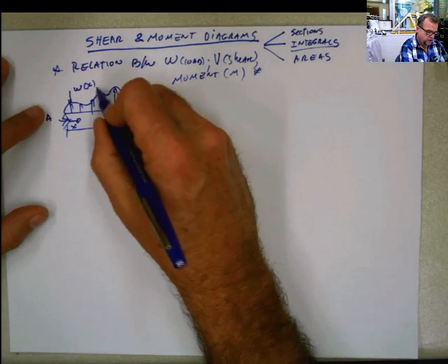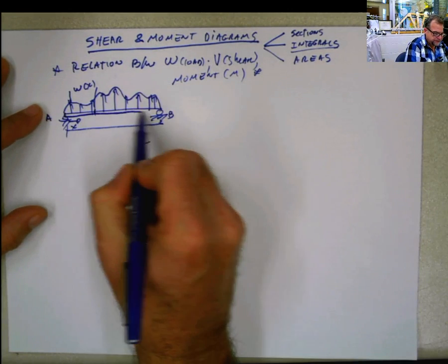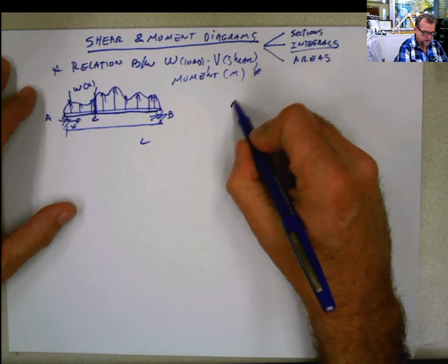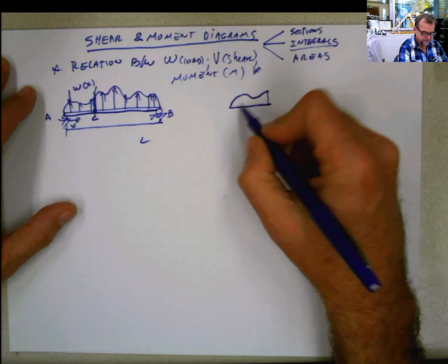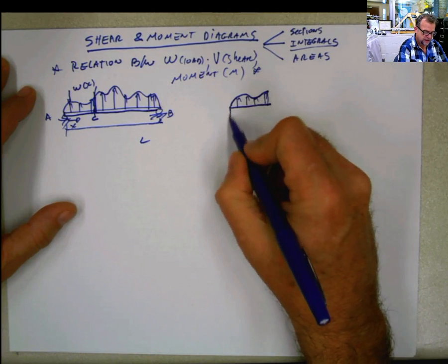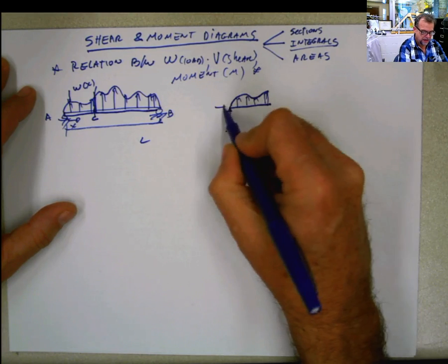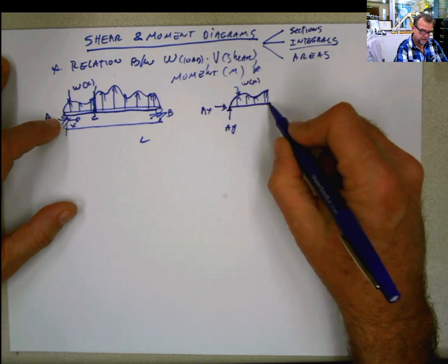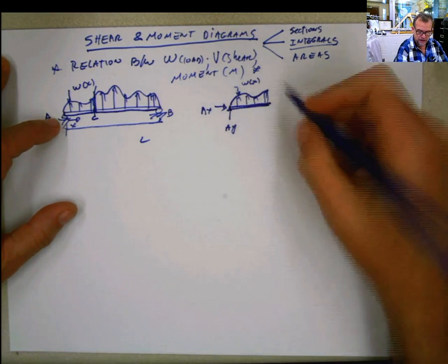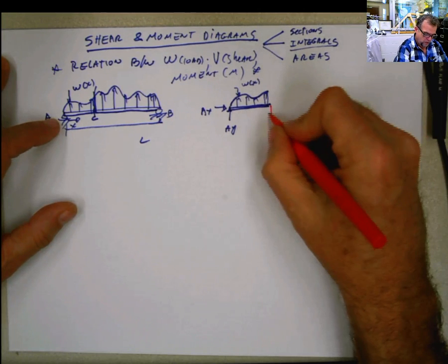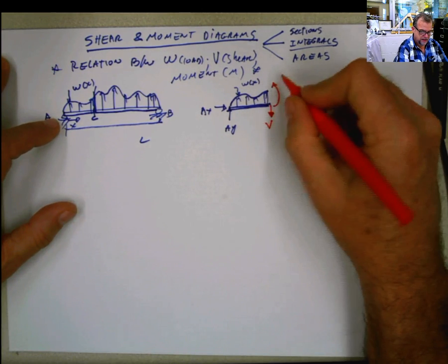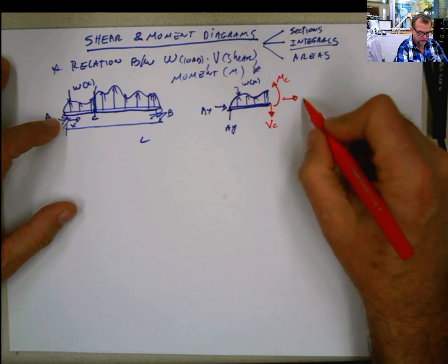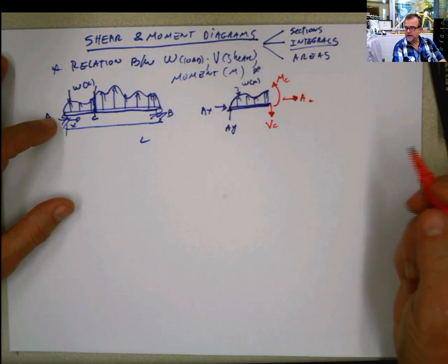previously, if we wanted to calculate the value of the internal force at a point C, what we did is make a section at that point. Remember, making a section means that you cut the beam like that. This is the point A with your reactions Ay and Ax. This is the same function w, and this is the point C. When we do that cut, there should appear one shear force, which is the positive convention, and the moment at that point. You're also going to have an axial force here in C. That's basically what we said last class.